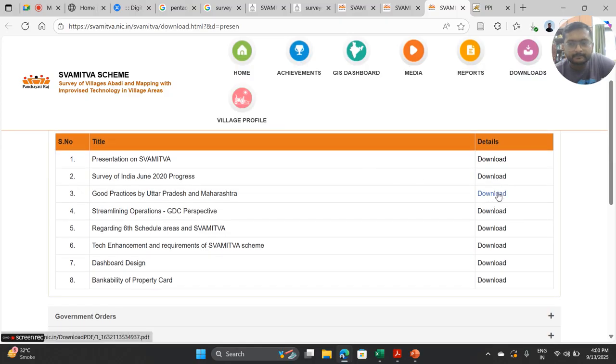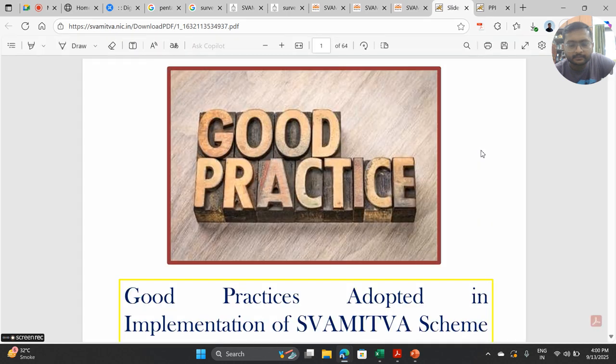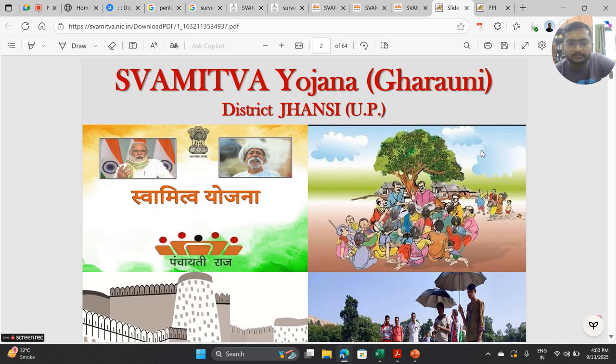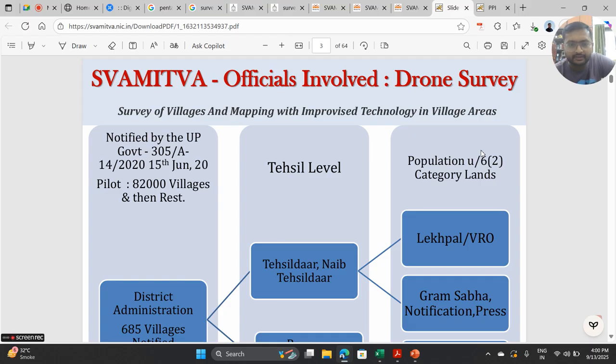If I'm not wrong, we use CORS for corrections. Yes, we need georeferencing. To avoid that, what they did is they fitted a GPS chip inside the drone and collected the data. But GPS accuracy is not that good every time.